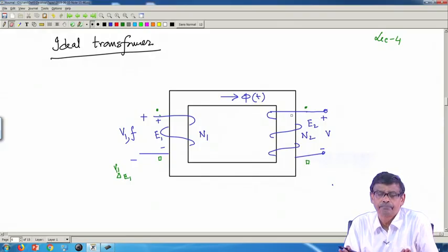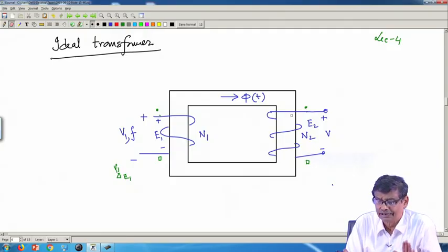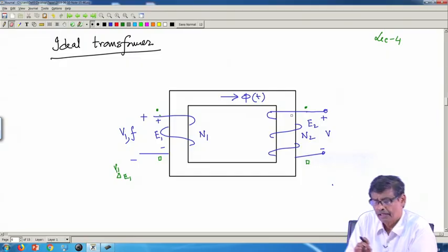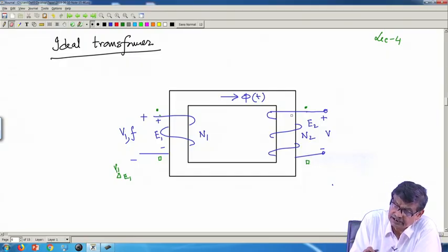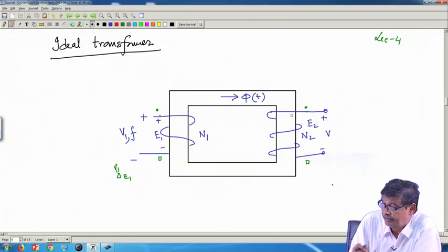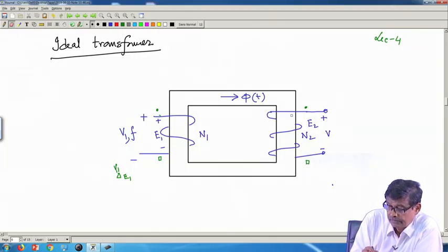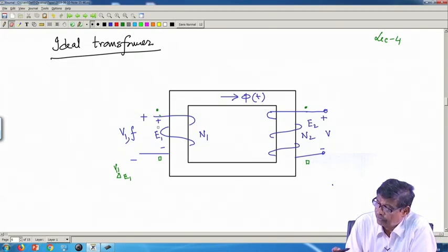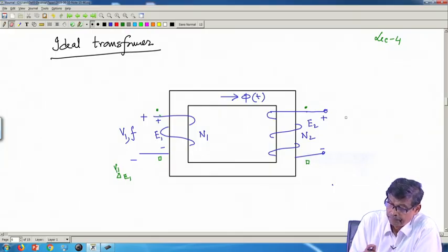in place. One should not be thinking this way, that way. Apply a given voltage at a frequency, the RMS value of the induced voltage and its polarity with respect to this plus minus, all things are now drawn, the instantaneous polarities plus minus. Then the secondary instantaneous polarity is also this one, and V1 and E1 will be same, there is nothing in between.